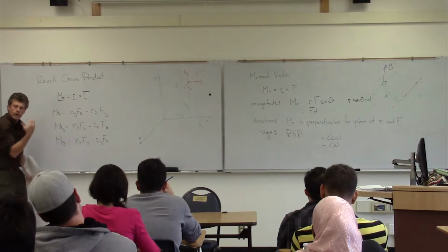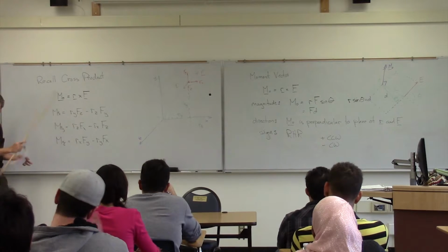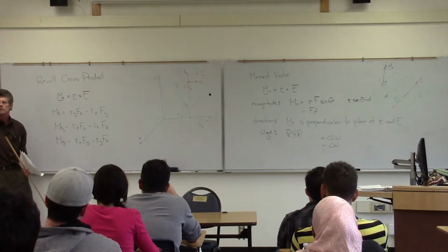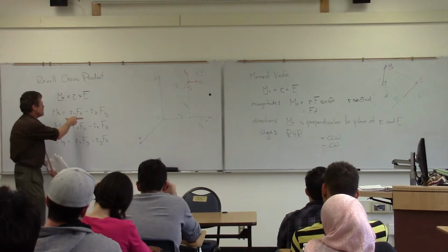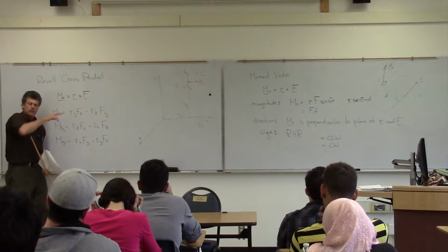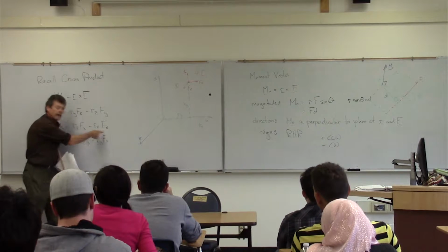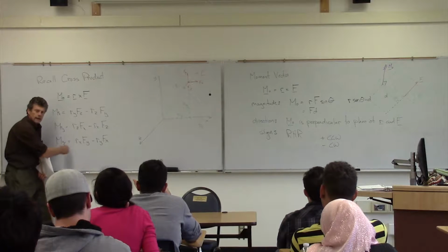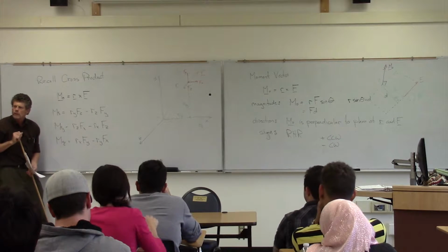Come back to this equation. So there actually is a way of solving this as a scalar. And I want you to think about that. I mean, we can plug and chug stuff into equations, but think about what the pieces are meaning. So that's what that piece means, and we can do the same thing in the y direction and the z direction. And that's why we never see anything related to y there. It doesn't twist about the y. We don't see anything in the z portion there, because that doesn't cause any twist about the z.